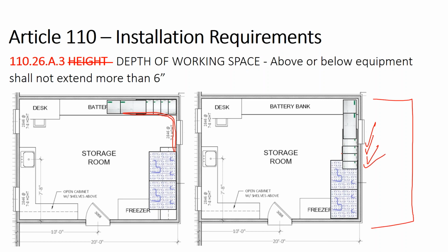One issue to keep in mind is that with the National Electric Code, generally you don't run into this, but there's a rule that says the front of this inverter, which is about a 9-inch depth, cannot stick out more than 6 inches past the next electrical box, if they're stacked within the same plane.